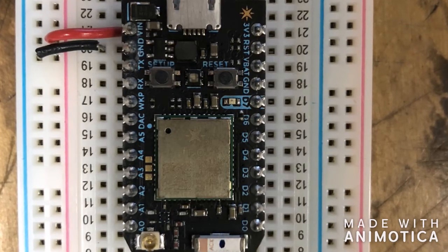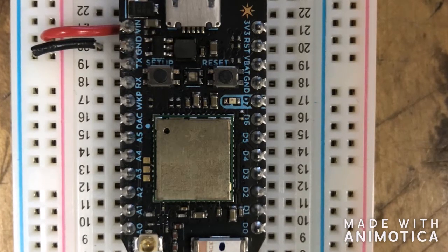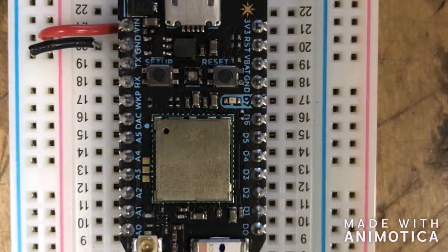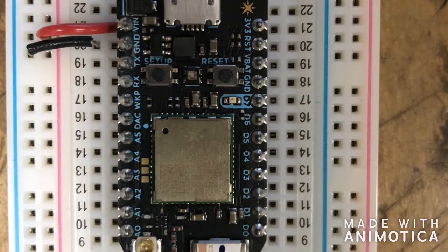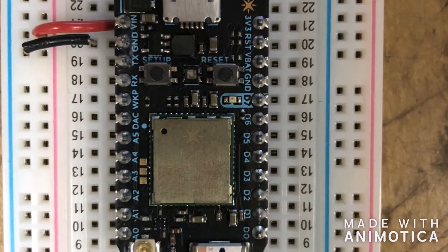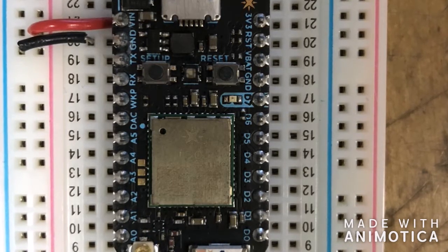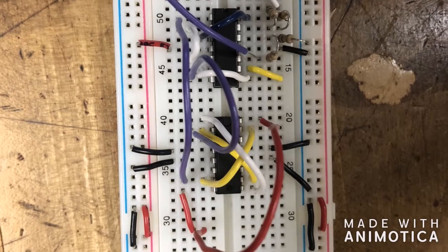The Tinker app that goes with the Photon allowed us to set the pins as digital read or digital write, or analog read, analog write. We used pin A3 as analog read, analog write. This allowed us to have a range from 0 to 4095, which translates to 0 to 3.3 volts.